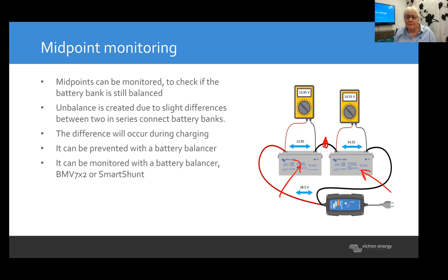Also, I forgot to mention earlier, when you make a big series-parallel battery system, start with full batteries. Don't start with half-empty batteries. Start with the whole bench full. Maybe individually charge all the batteries and then marry them together. That's also really important for lithium systems as well. It's important to start with all the batteries full. For any multiple battery system, it's a good practice.